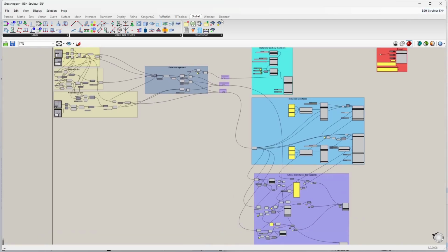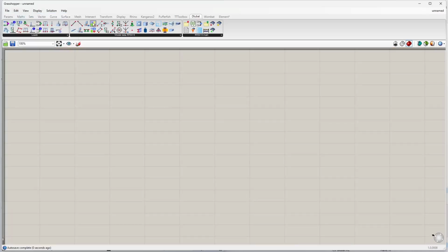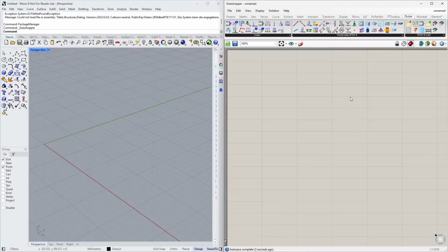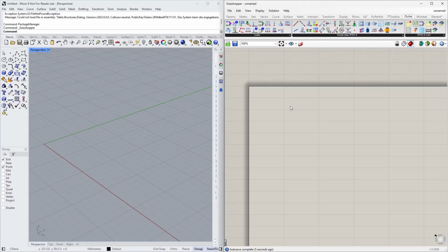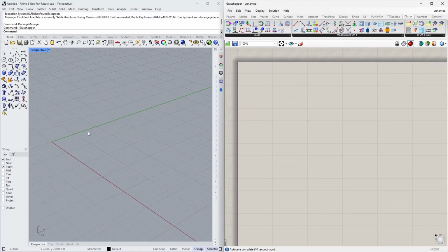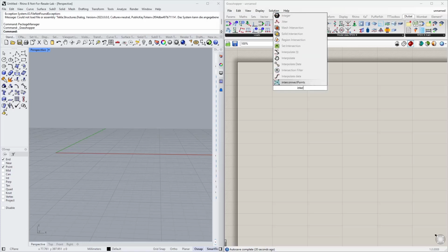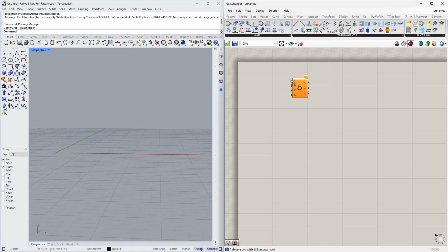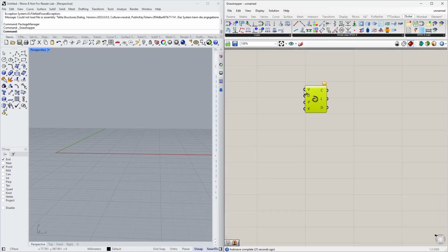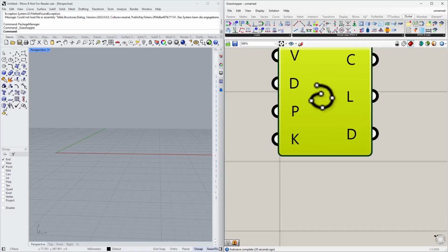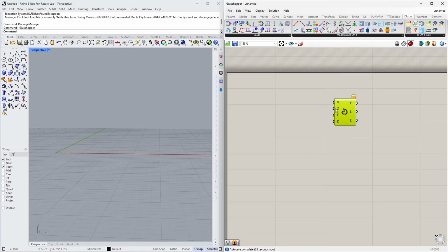All right, so let's create a new file in Grasshopper, move it to the right hand side of the screen, and start with the modeling. As I said, I would like to begin with the Grasshopper algorithm, so I need a plan how to model that, and I will start with the roof. The roof was curved, and therefore I need some kind of a curve with the interpolate component. The interpolate component requires the nodes. You can see it basically on this little icon here. You need to define the nodes and then it will interpolate a line or a curve.